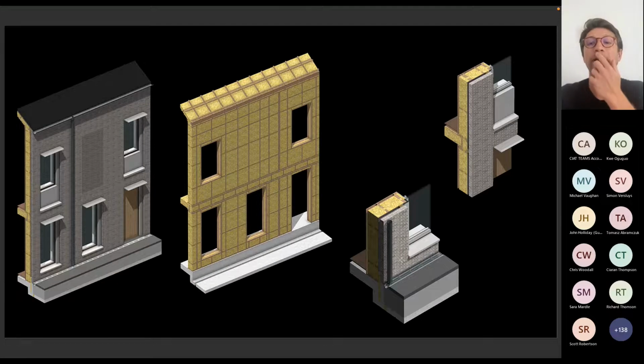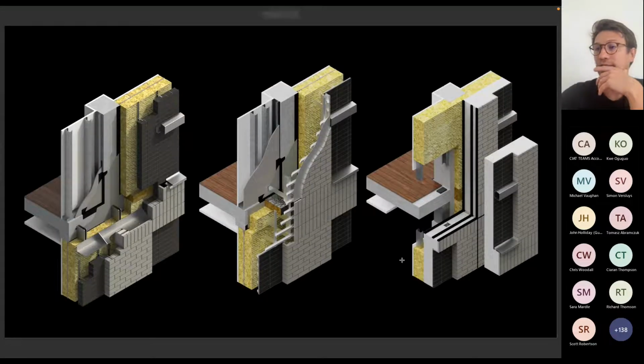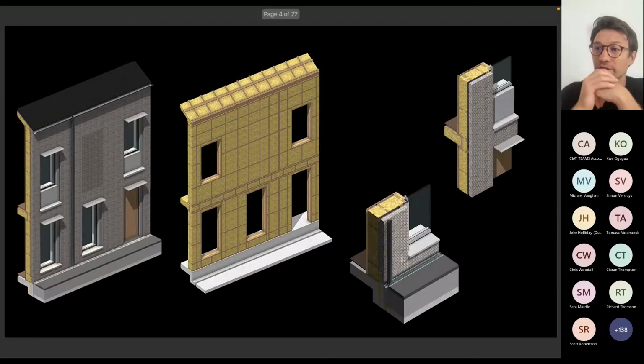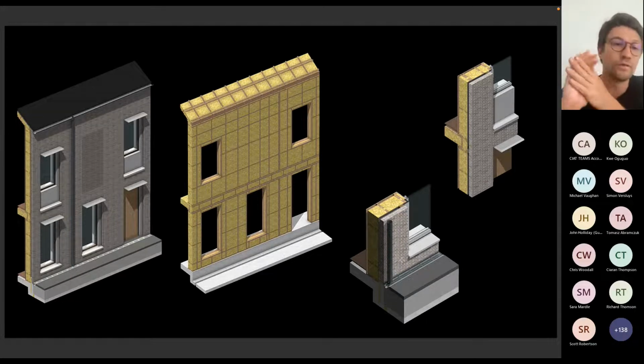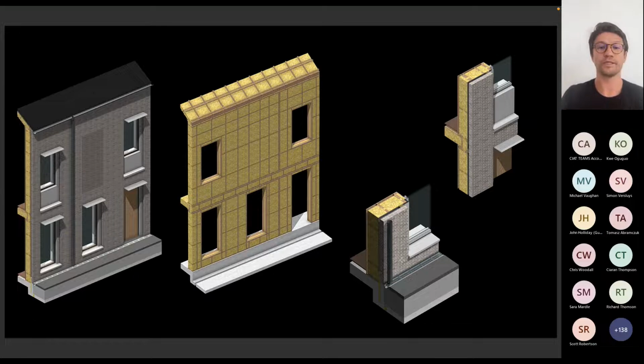But it's far more complex than that. The main parameters would be the height of the building, fenestration layout, a brick pattern or bond, as well as thickness of the wall in relation to its thermal performance, and availability and quality of labor and skills available in the region where the project is.